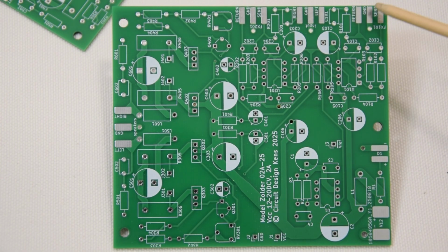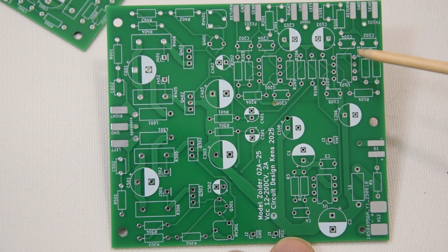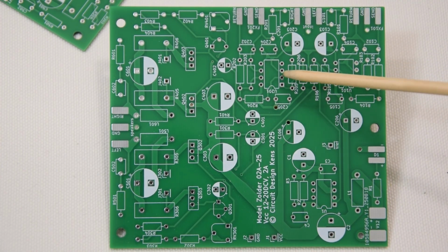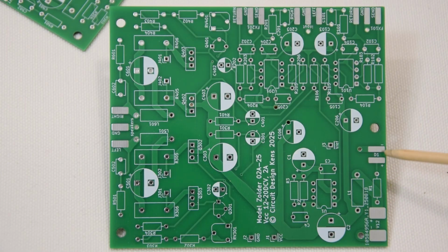So this is the part where these signals come in. And this section is the input section where the amplification takes place. These are the positions for the 2 op amps, for the left channel and the right channel. And they're isolated from the power supply section, where the filtering of the incoming power supply is done and the reference voltage is created and stabilized. You see positions for the caps to do this.